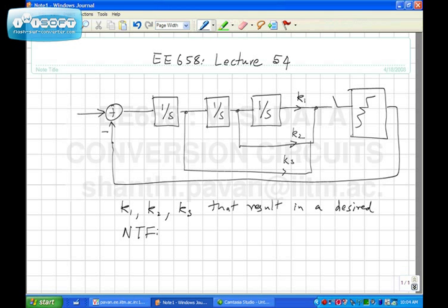You've already seen how painful it is to simulate. You've done a 4-bit flash, correct, in your assignments, so you know how long it took, and for a 4-bit flash you can run only a 64-point FFT or something and you'll still be able to see clean results. Whereas in a delta sigma we said that the number of bins you require in the signal band should be substantial. If you use the Hanning window, the signal itself will leak to 3 bins. So if you want this to be at least 20% of the total signal band, then you need to have at least